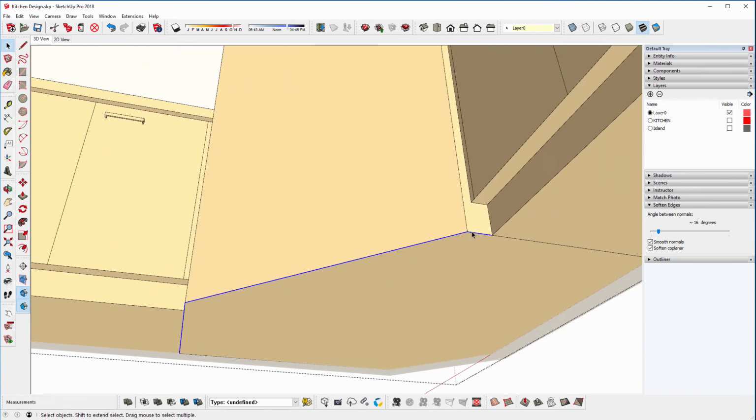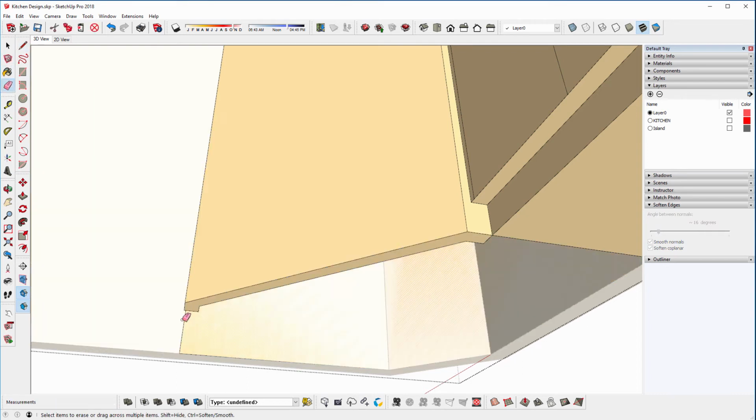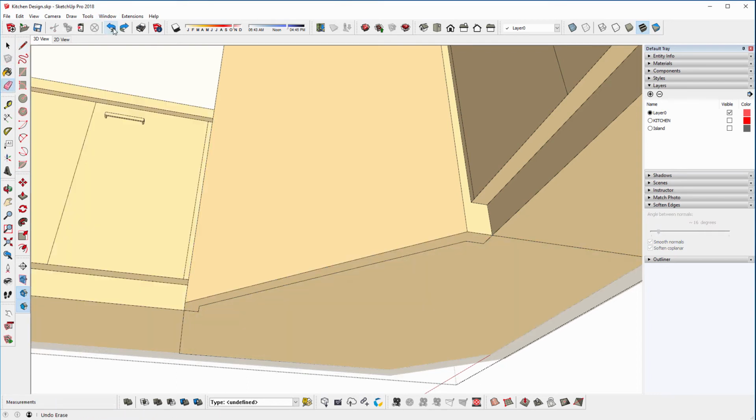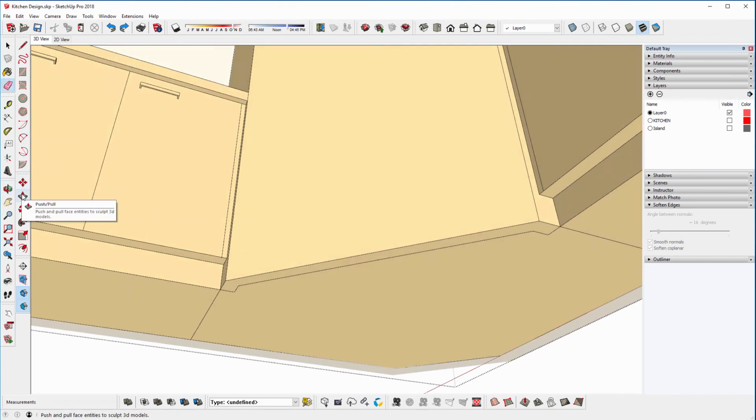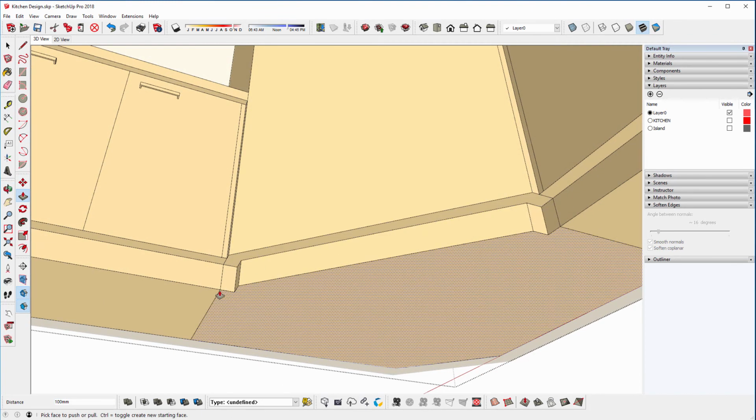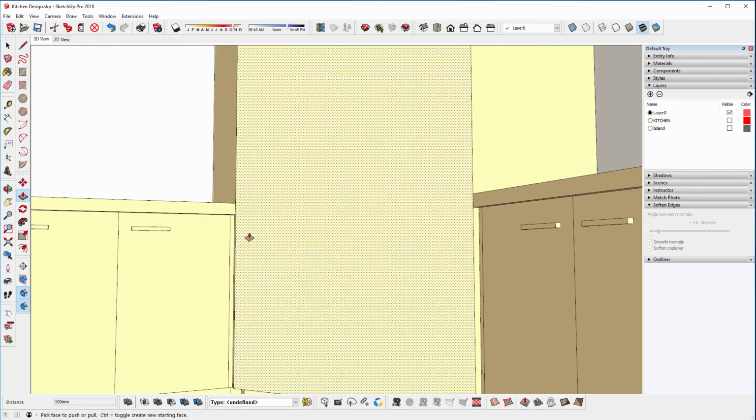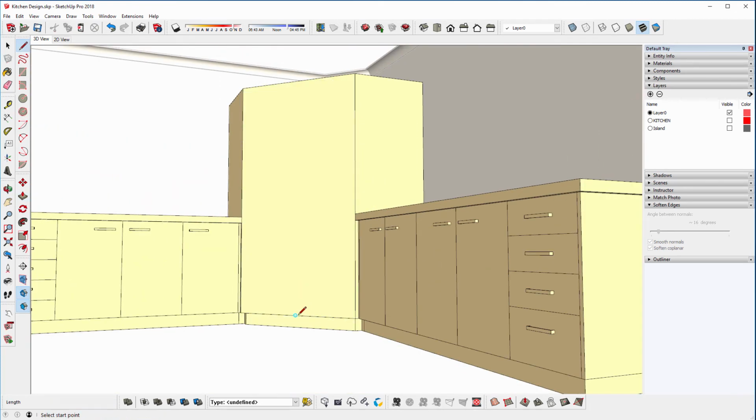this here. So go offset tool, bring that in 50, and then we just get the line tool and just break that there, and erase that line. Be careful to not delete that one because your group and your line will disappear. And then you could pull that up 50 as well. Sorry, 100. And then we could just simply add a line in there like that. And we'll just borrow these two here.